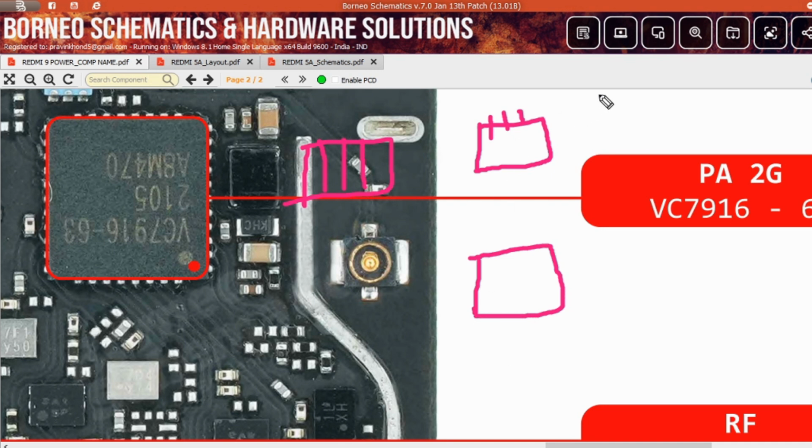So when someone calls you, that means the RX section works, the receiving section works. Then the antenna switch directly connects these signals to the RF IC. Clear? When you call someone, that means transmitting, then the TX signal works. Then the RF signal through the RF IC comes to the first power amplifier PA, like a 2G PA.